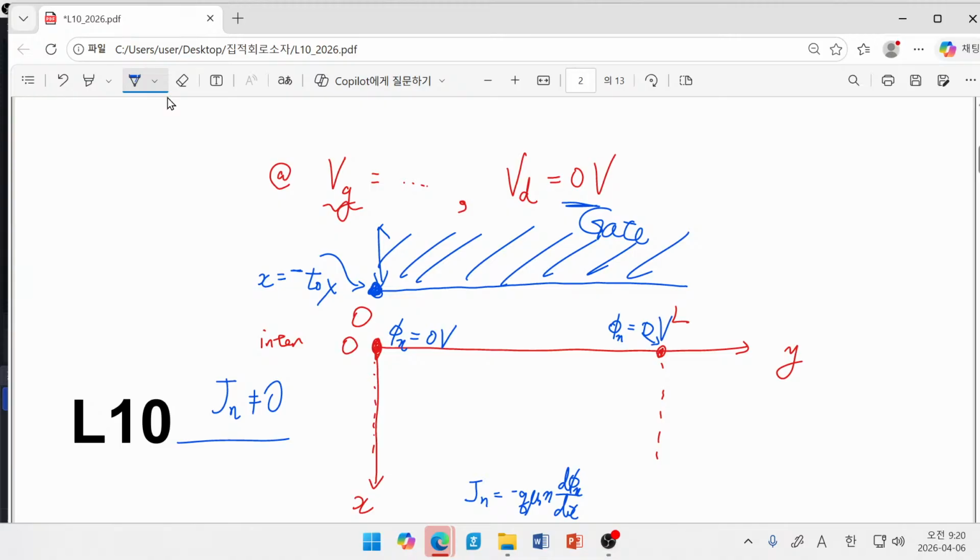The answer should be that over our y-axis, our quasi-Fermi potential at this specific 0 drain voltage should vanish, regardless of the value of your y position. So it is 0 all over our case.